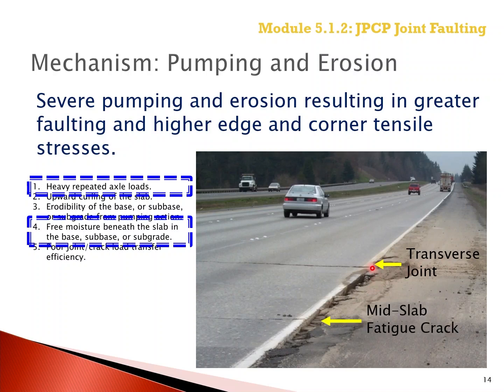Another point to remember relative to the fatigue cracking of the concrete slabs: when pumping and erosion occur beneath the concrete slab, that increases the potential for mid-slab fatigue cracking because the tensile stress at the bottom of the slab and top of the slab will increase, reducing the allowable number of load applications and increasing the potential or probability for mid-slab fatigue cracks.